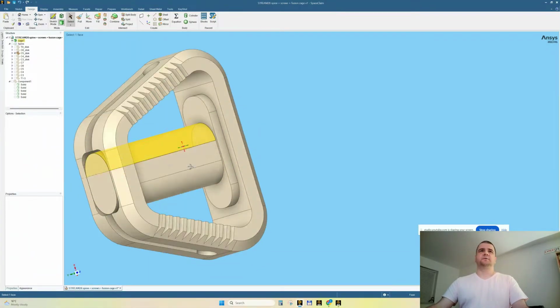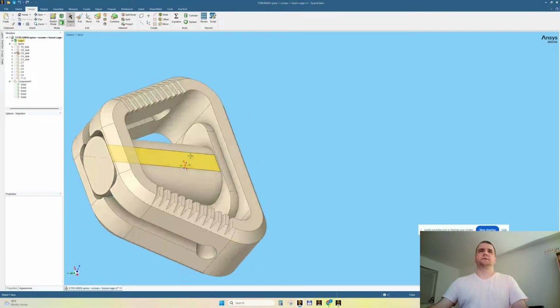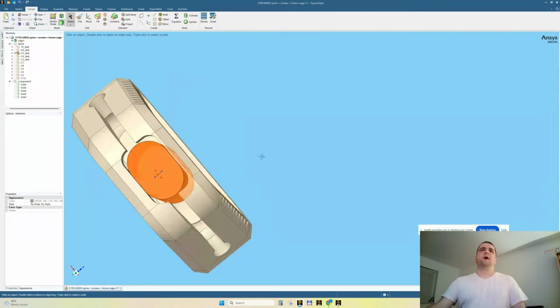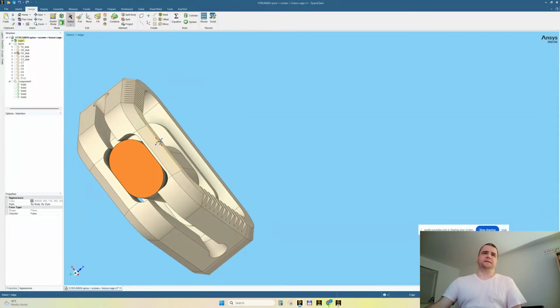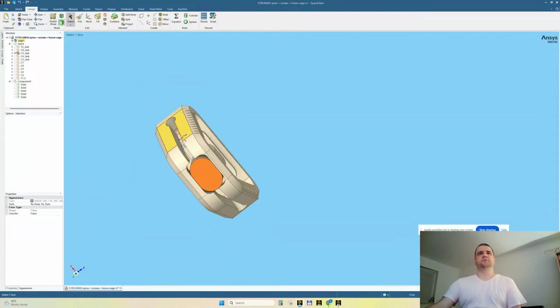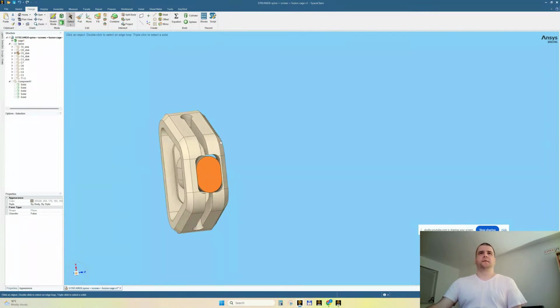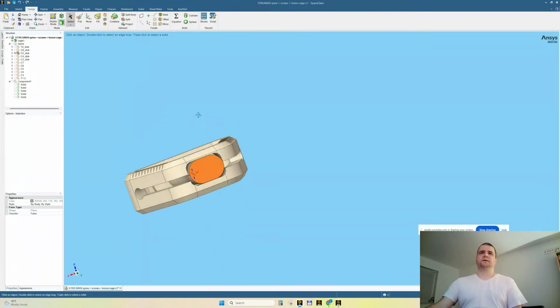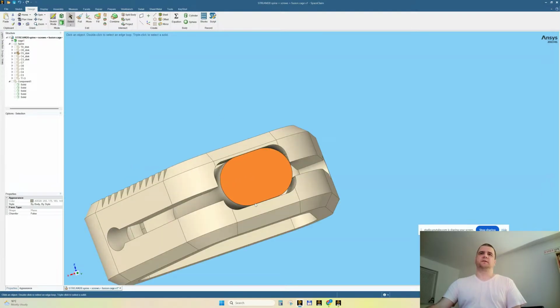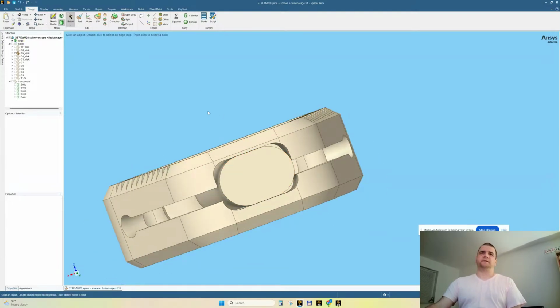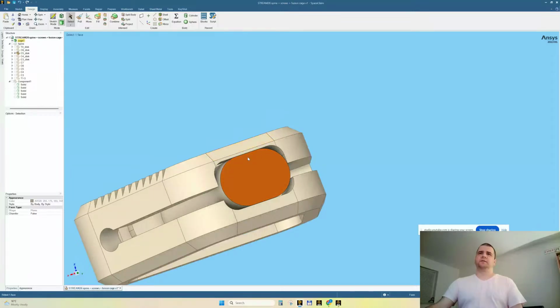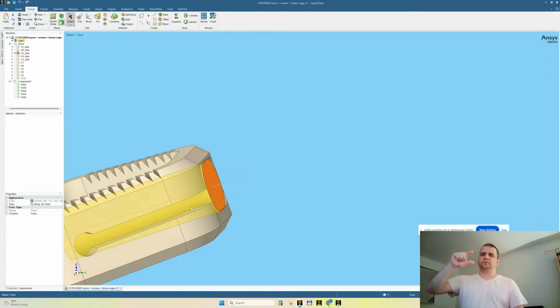Just for fun, is there a way to remove also this? Why am I talking about it? Because if I leave this, then it will not be flexible. This should be like a spring. Yes? Because there will be a top compression, let's say, or from the bottom. If I have this big protrusion here, it will limit the spring effect because I would like this gap to close. Now it's like this, and because I have this in the middle, I am limited.